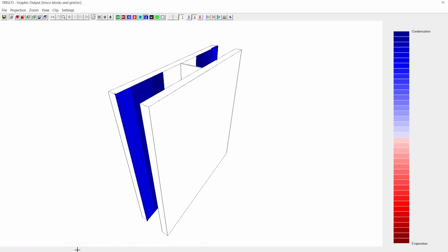At the level of the thermal bridge, in the middle of this component, the temperature on the exterior side of the insulation is warmer, avoiding interstitial condensation for this example. The color gradient for the result you see here is only a relative color but not an absolute index. You will better visualize this in the later part of this video.